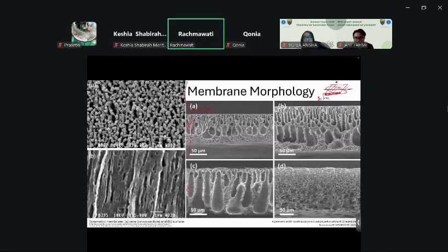And then this is the second one. This is the asymmetric polyether sulfone membrane, and it's actually bicontinuous. So you can see that. This is also the cross section, the thickness. You are seeing this from the side of the membrane, so not the top of the membrane, not the surface, but the cross section. So you can see that it has different regions. For example, you have this, but this one is dense, and so on. So you can see the difference between the symmetric and asymmetric types.